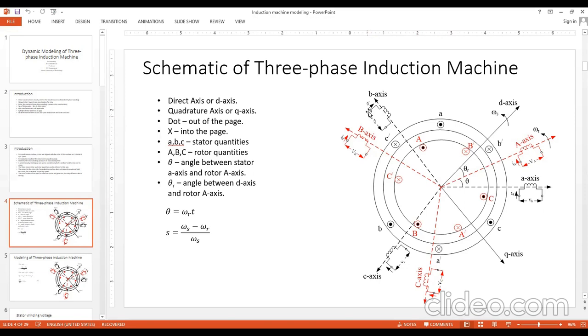If you look closely into the direction of current flow through the coils, you can clearly see that all these three phases are carrying current into the coils. That is basically the motor convention, meaning we are supplying three-phase power into the three-phase balanced set of windings in the stator coil.